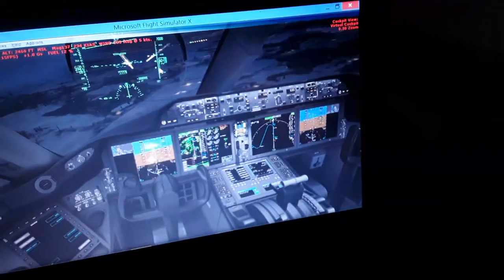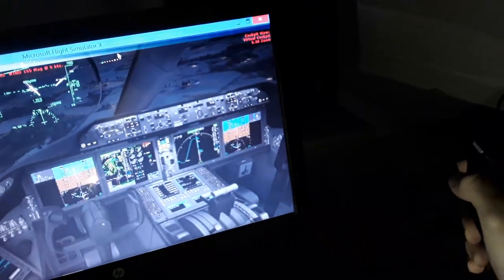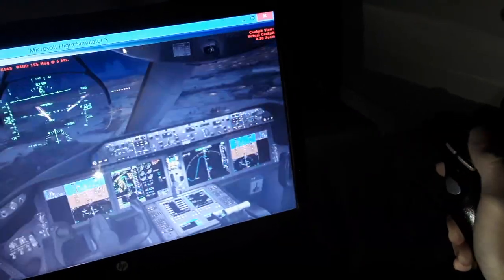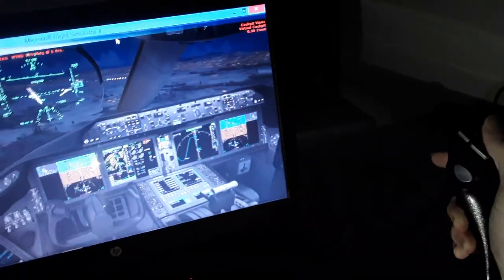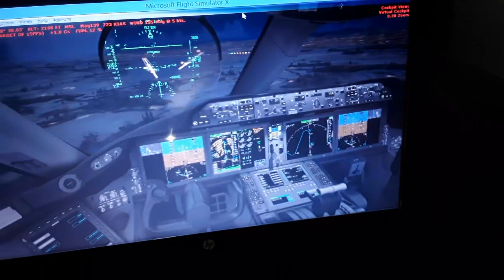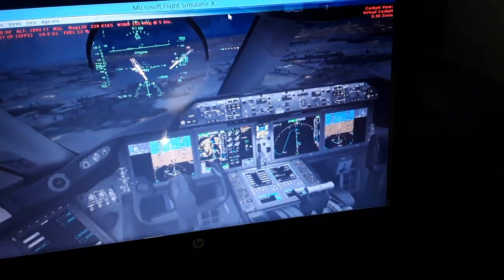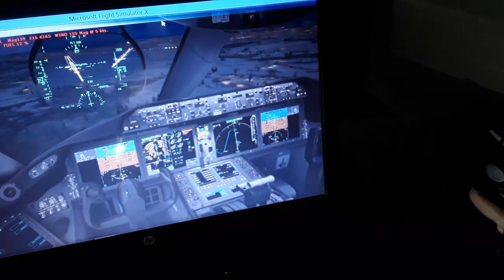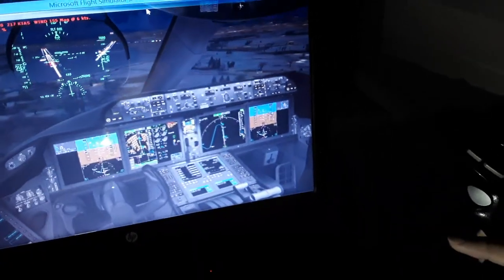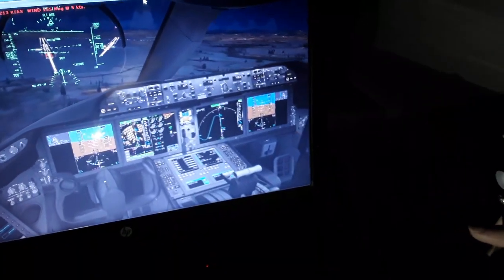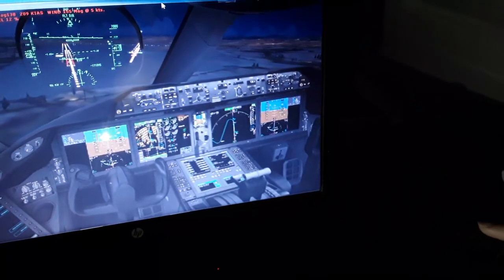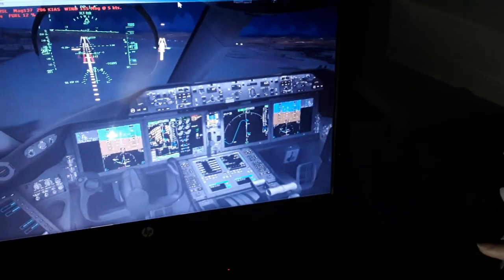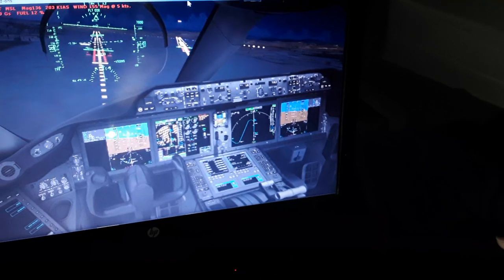A little bit less thrust over here for the engines. So right rudder now again. So we have wind gusts and side wind to align the aircraft with as we approach for landing. A bit more or less idle as we are approaching. Align with the center line and leveling off for approach and landing.